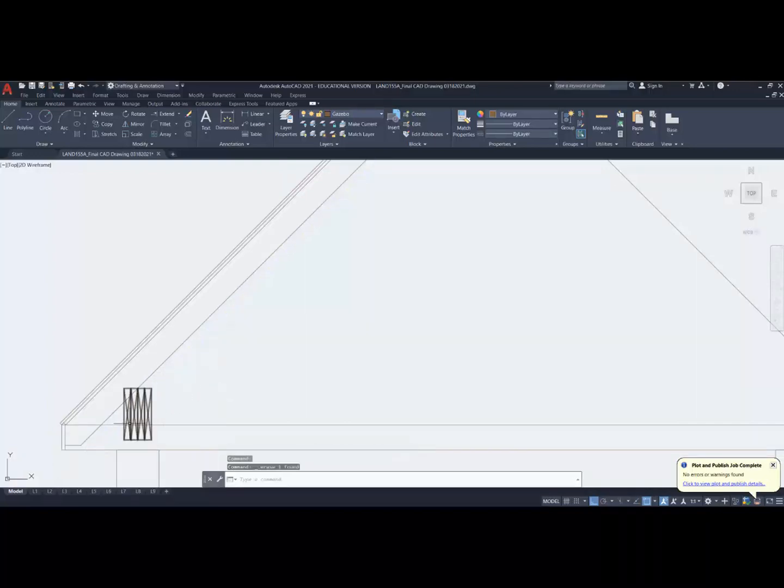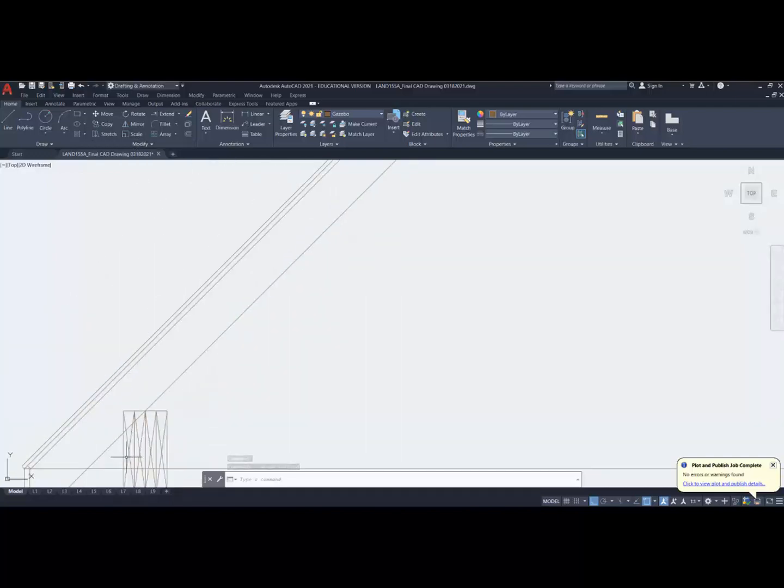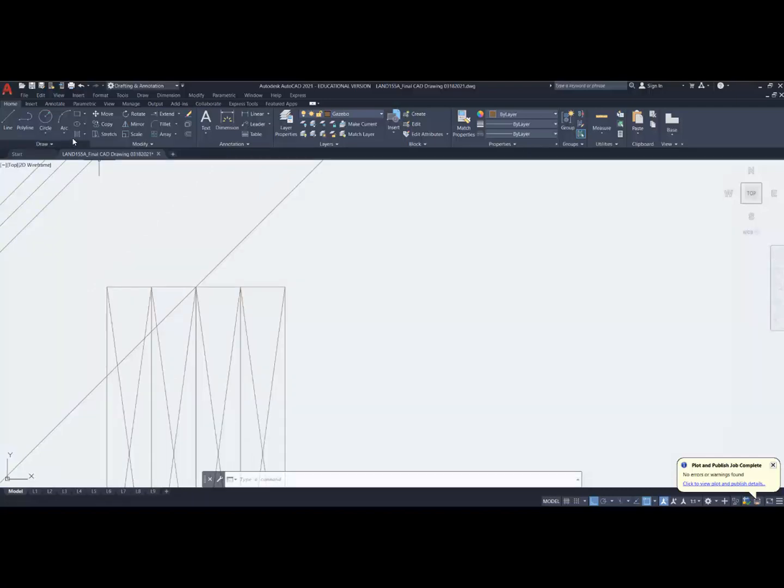I'm going to stick to my decisions that I made earlier, and now I'm going to take this line and trim it. Now, this is a single entity. There's a couple different ways I can trim. Like any time we're creating something, I want to introduce new elements. This is the break command, and the break command allows me to pick a line and then pick 2 points. And what it is actually doing is breaking that line in that specific area. But notice I've gone onto the left side of it. The better way to use this is this. I'll select Modify, Break.